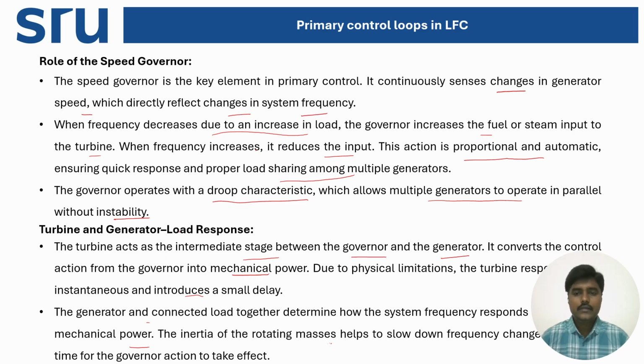So whenever the load changes, the turbine and generator cannot respond immediately, because they are mechanical things having a heavy mass, and they exhibit some kind of inertia. Due to that inertia, they also have a time constant, which needs some time to respond.